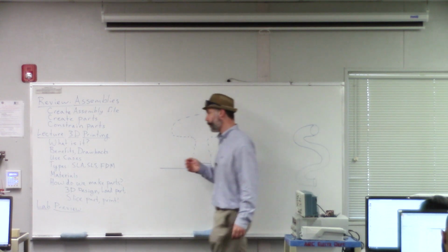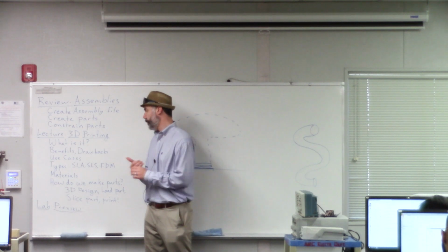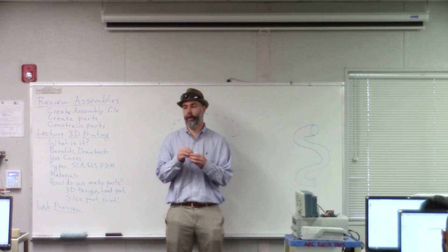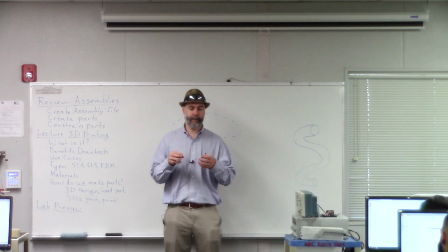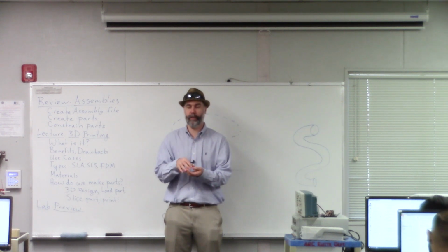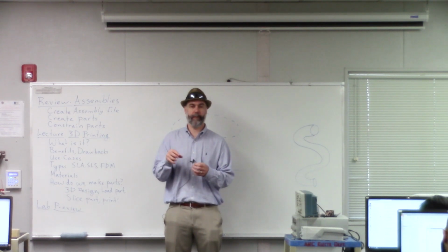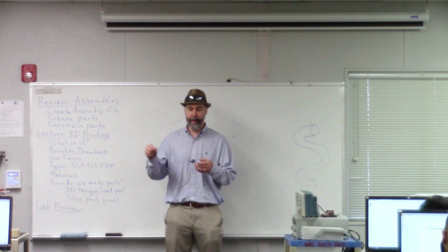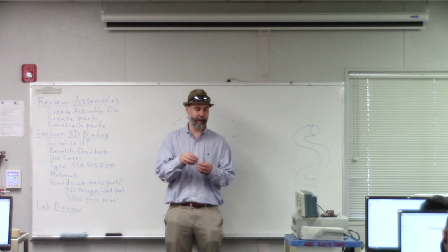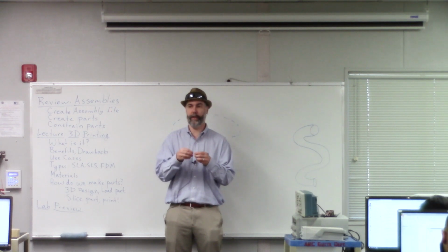Jewelry is another use case. It's possible to print in metal in some cases, but also you can print in plastic and then use that as a form for something called lost wax casting. So you make that form and then you pack sand around it, and then you pour molten metal in, like molten gold or something like that, and it melts away your form, but it takes the place of that 3D printed part that you made, and then the metal cools in that shape.